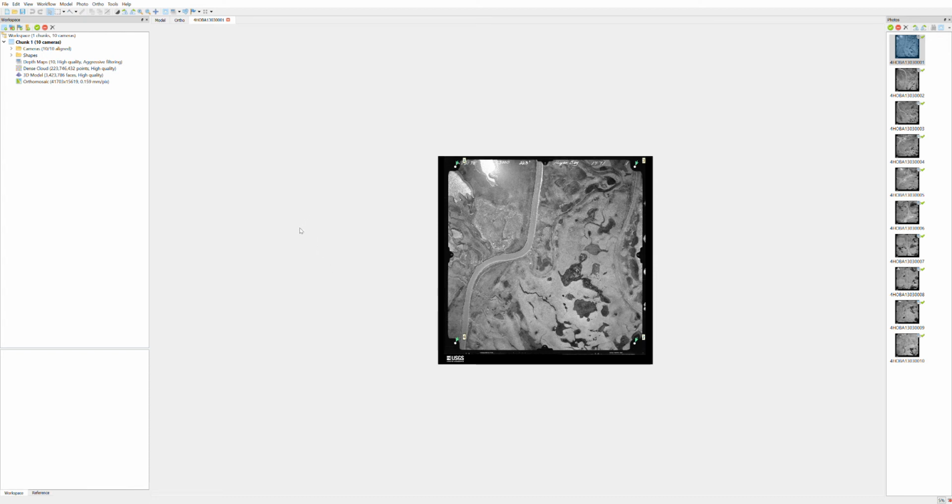So fill out your fiducial coordinates, and that will tell the program a lot of information about the camera lens. There is this pixel size, which we're not going to fill in. This is a measurement of the actual size of the physical pixels on the camera sensor, and so it would be a very small number, like 0.02 millimeters. But the program should be able to calculate that now because it knows how many pixels are between these fiducial marks, and then it knows the distance between the fiducial marks now. So it should be all good.